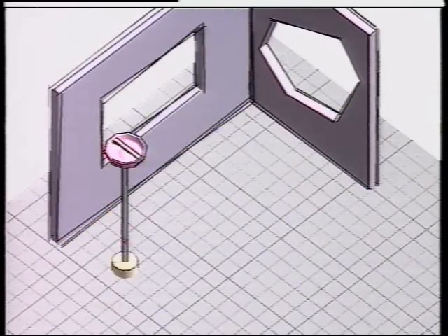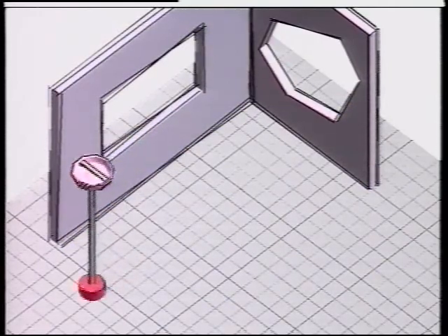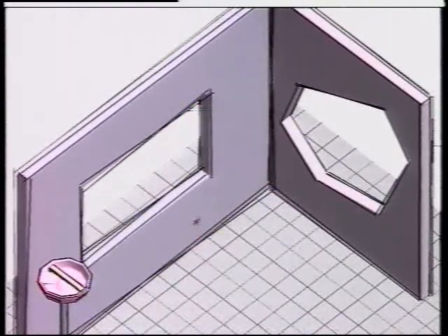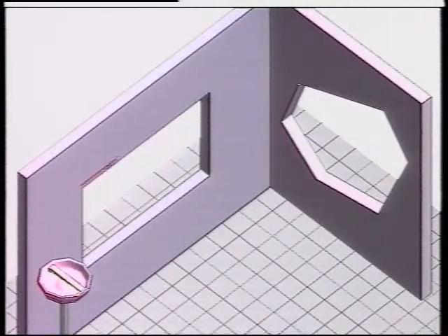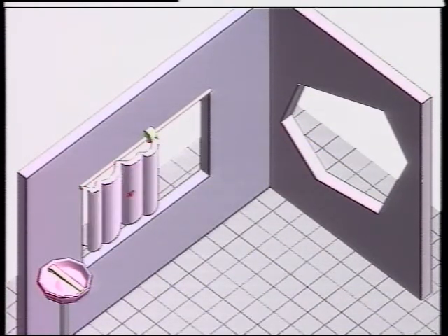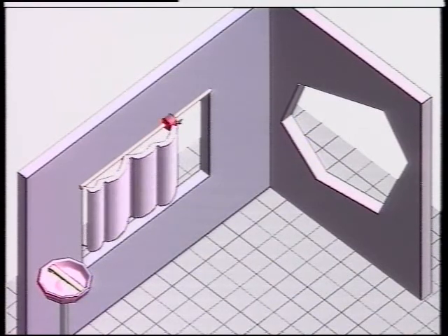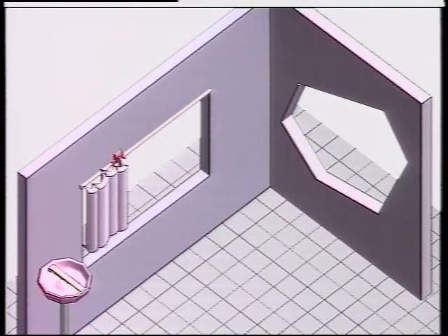We can also edit objects more dynamically. To create a resizable curtain, we first draw a curtain rod above the window, and then a curtain ring. The curtain ring is placed initially tangent to the rod, so we need to translate it back along the viewing axis to be concentric with the rod. Using a double click, the ends of the curtain are attached to the wall and to the ring. Whenever either attachment point is moved, the curtain automatically resizes to maintain the span.